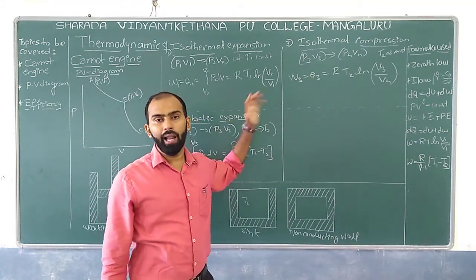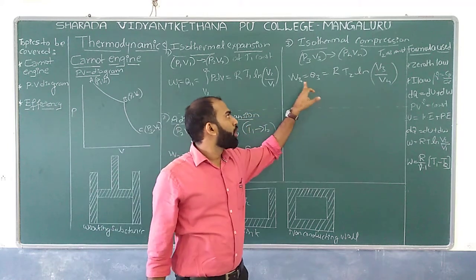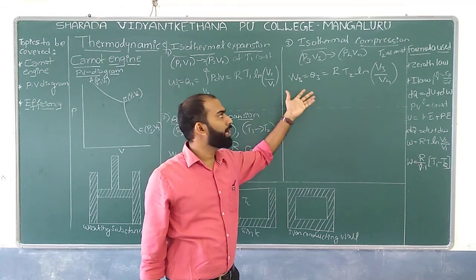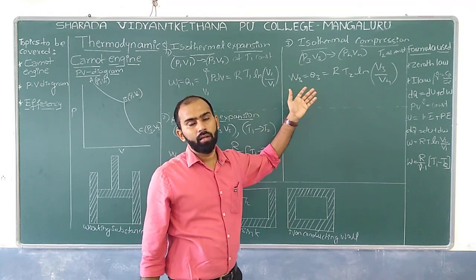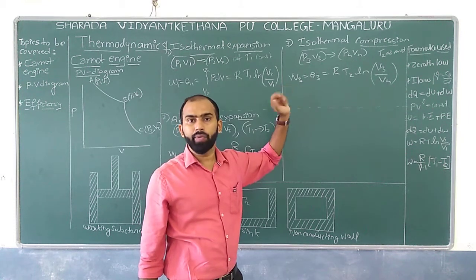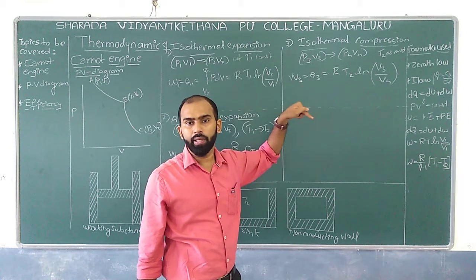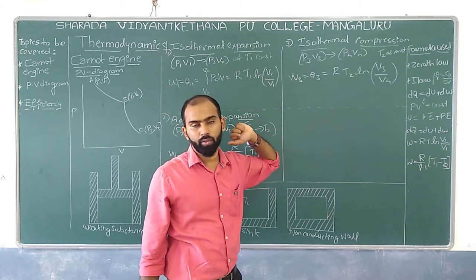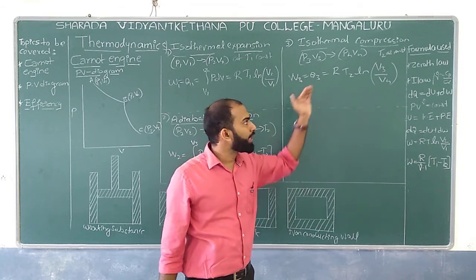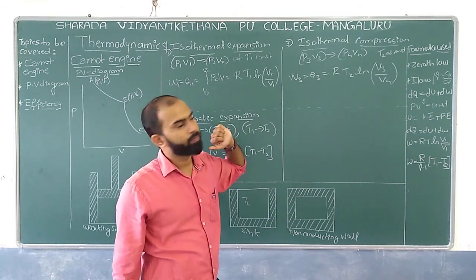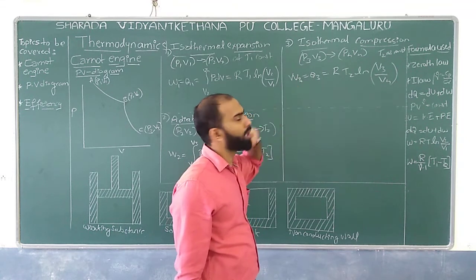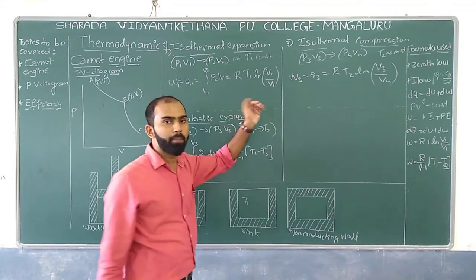It is as simple as because work is done on the system, means a minus comes over here so that it becomes log of V3 minus log of V4 over here. So that's why, because plus into minus is minus, V3 by V4 comes into the picture. Okay? Well, so this is what exactly we can have under the concept of isothermal process, isothermal compression.